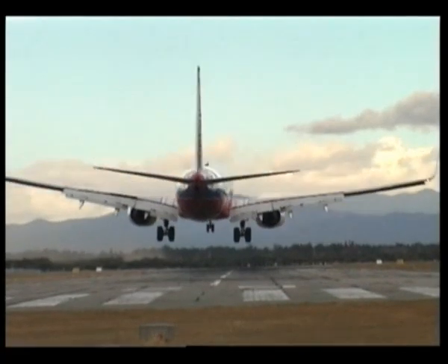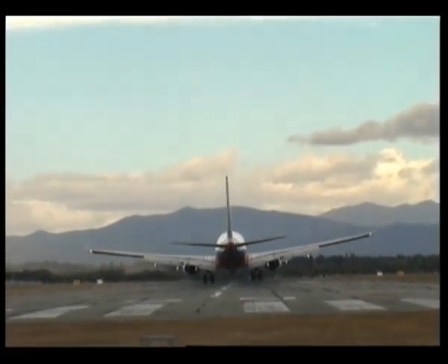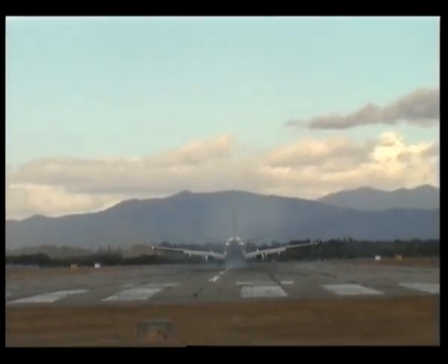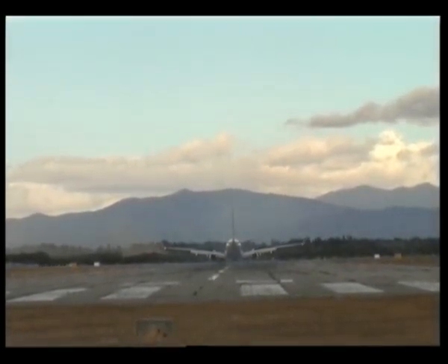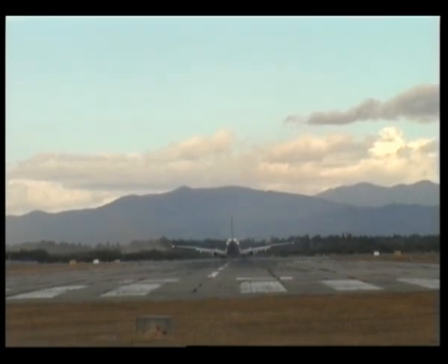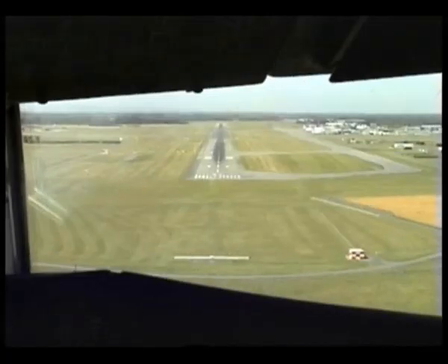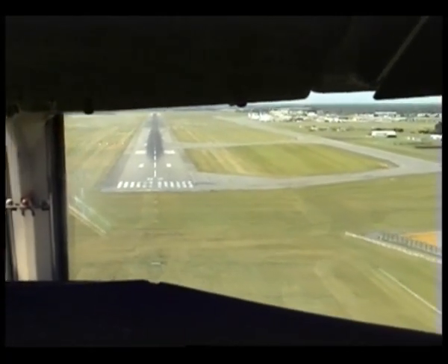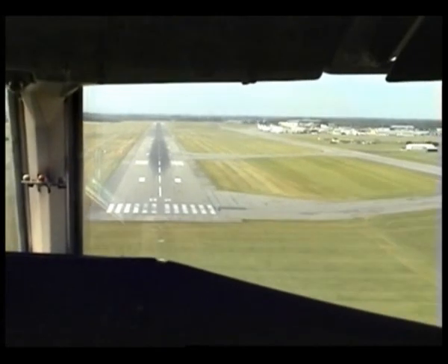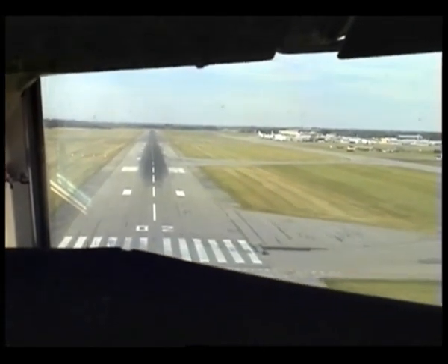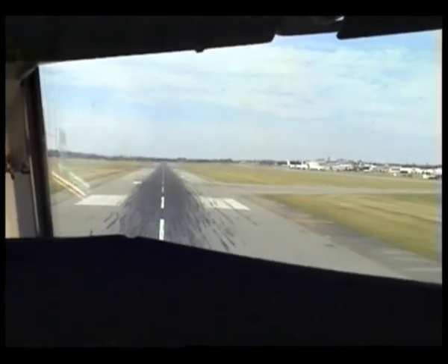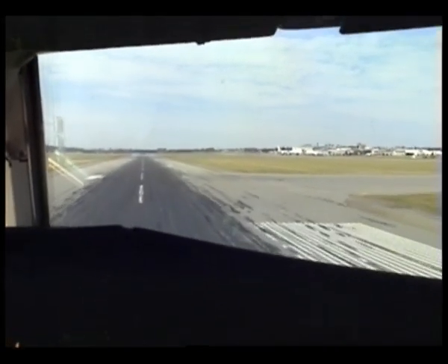The length of time and runway it takes to bring the aeroplane to rest after landing depends on its touchdown speed, which will depend on a number of factors such as weight, how the aeroplane is configured, and wind strength. Obviously, a strong headwind component will also have a greater effect on the aeroplane's speed along the runway. Theoretically, we want to land at the slowest speed possible, yet still have total control of the aeroplane.